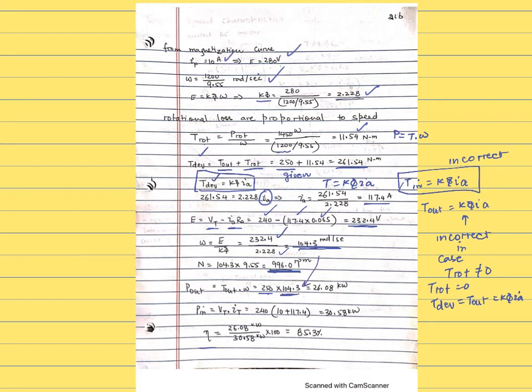And the input we already said is the terminal voltage times the terminal current, so 240 times the field current, plus this is your IA, so that's your IT. So P output divided by P input gives you the efficiency. You might have some other ways to calculate it as well, so it's fine if you use different methods than this.